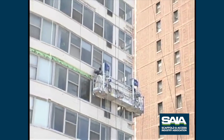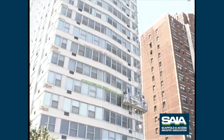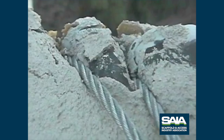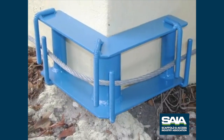Always keep the suspension rope vertical above the hoist. Wire rope which hangs below the hoisting machine must be free to rotate to prevent bird caging. Always use thimbles and shackles. Never terminate on a sharp edge. Protect against cutting and abrasion.